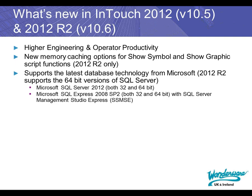The later versions of InTouch support the latest database technology from Microsoft. 2012 R2 supports the 64-bit versions of SQL Server: Microsoft SQL Server 2012 both 32 and 64-bit, and Microsoft SQL Express 2008 SP2 both 32 and 64-bit, with SQL Server Management Studio Express also supported with the later version of InTouch. As part of the InTouch installation, SQL Server Express will be installed if SQL Server is not detected.